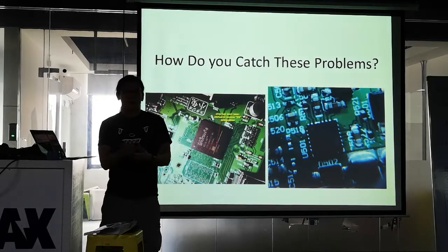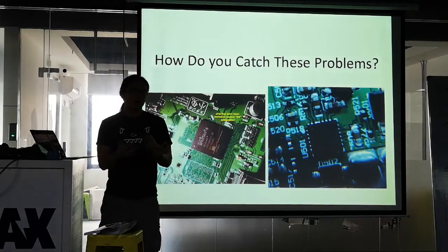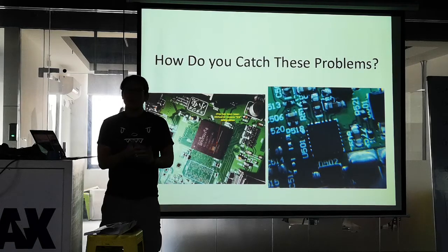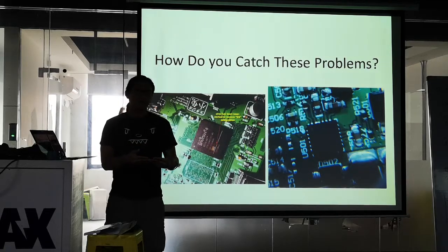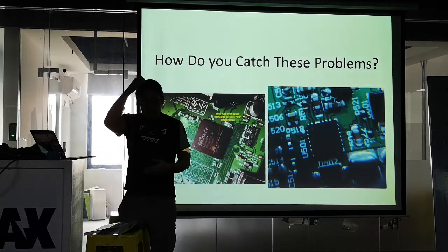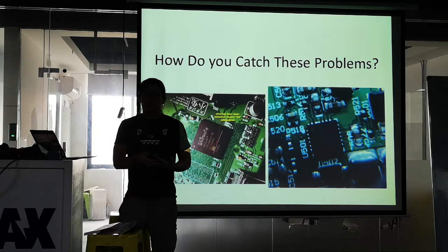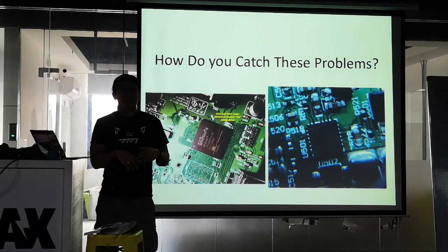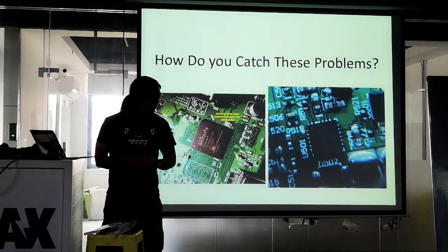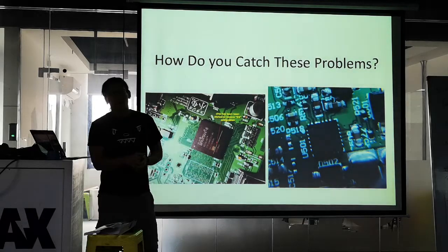And so the distributor was blending these fakes into the supply chain at a rate of about 3%. But my particular application cared about the silicon ID code and wouldn't boot unless the silicon ID code checked, right? So I caught them at this particular game, and eventually we had big arguments, and that gave me new FPGAs. We were able to replace them. But these types of problems do happen. It's a really subtle one.